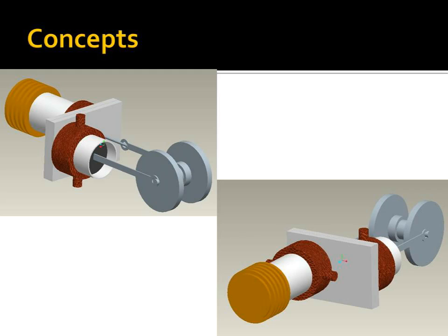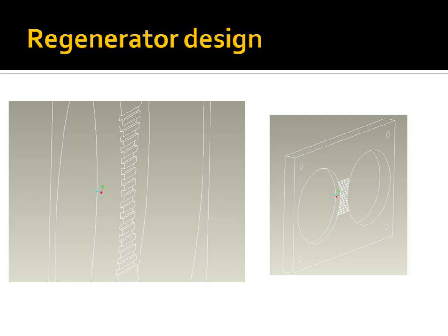Also, on the lower scale in terms of displacer efficiency, we have the obvious choice of aluminium or brass. But I want to try and stay away from that, and try and get the displacer piston working with optimum efficiency. The regenerator design here, as you can see, is a manifold plate where the fluid will be able to transfer between the cylinders, going through the microchannels. This is my current regenerator design.